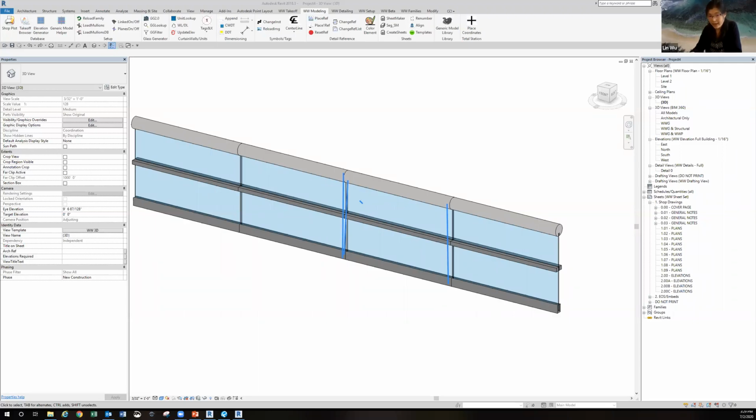When you don't have middle support, first of all, you shouldn't put a line over here. That offends building code. My point is, you should have at least one single metal bar to carry 3 lights at the same time. That's building code. Also, if you have a return, for example a smaller balcony, you don't have enough room to get 3 lights over there. At a corner, a transition, or the end of the bar, the jam condition, you always need a metal support over there. So how are they going to draw a metal vertical support post? You can talk about it in the next section.